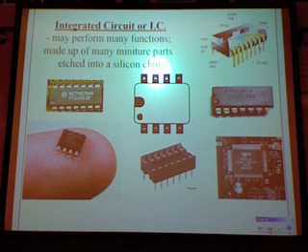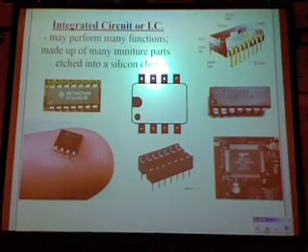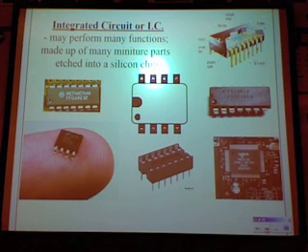Well, those two things are your indication about what number each of these connections are. These connections are called pins or legs, and some of them have a whole bunch of them. And when you use these in a circuit, when you add these to other parts, I need to make sure that pin number 1 is hooked up to the right place and pin number 8 is hooked to the right place. So if it has a little dimple, that dimple will always mark pin number 1.